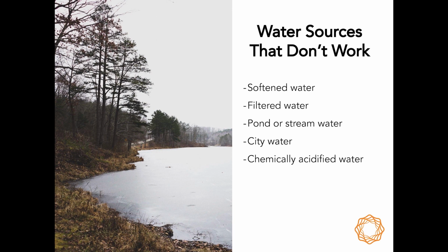So what happens is you put in an acid and the pH in the tank drops. But then if you were to leave that for a period of about 24 hours, you'll come back in 24 hours and you'll notice the pH has gradually come back up again, and it's right back up to a 6.8 or a 7, because some of those bicarbonates that weren't neutralized by the acids are now releasing and expressing themselves, and the bicarbonates have begun to bind and react with much of the acids that were there and neutralize it, and now the pH begins creeping back up again, which also means that you now have more available bicarbonates in the system.